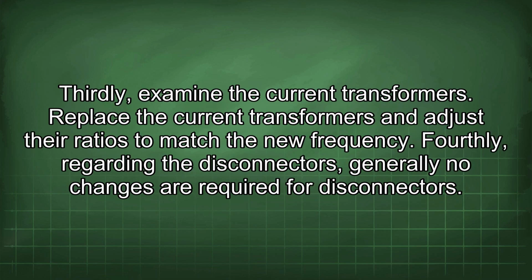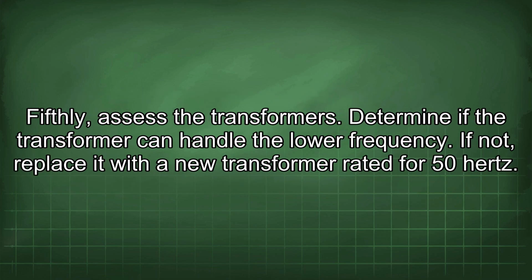Thirdly, examine the current transformers. Replace the current transformers and adjust their ratios to match the new frequency. Fourthly, regarding the disconnectors, generally no changes are required for disconnectors. Fifthly, assess the transformers. Determine if the transformer can handle the lower frequency. If not, replace it with a new transformer rated for 50 Hz.